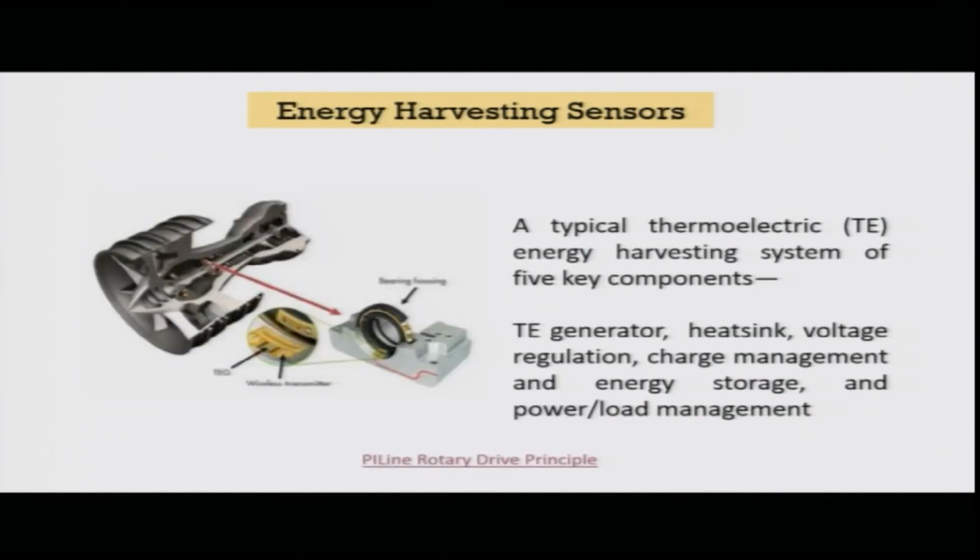There is another interesting device which is known as the energy harvesting system. This can be used for various purposes. For example, a typical thermoelectric energy harvesting system will have a thermoelectric generator, a heat sink, voltage regulation, charge management and energy storage.